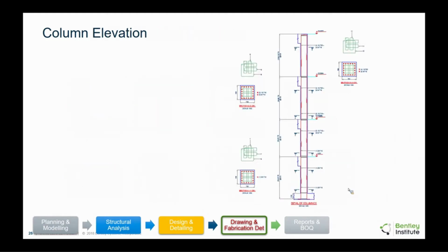The column elevations indicate the arrangement of reinforcement. Laps could be central at top of slab, staggered, or at the same level. They could be laps, or it could be mechanical couplers. So as project specifications vary, all of this will change with that one click.